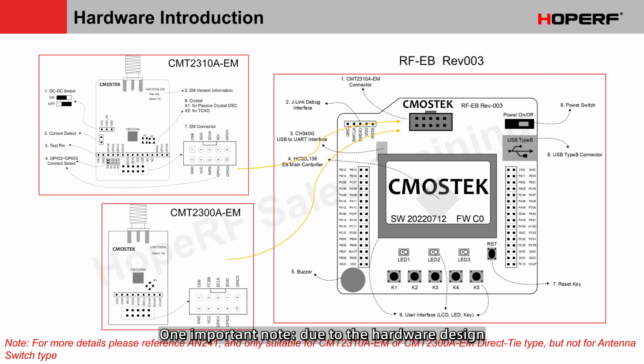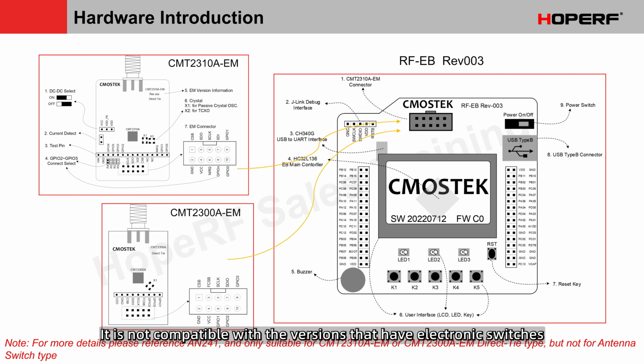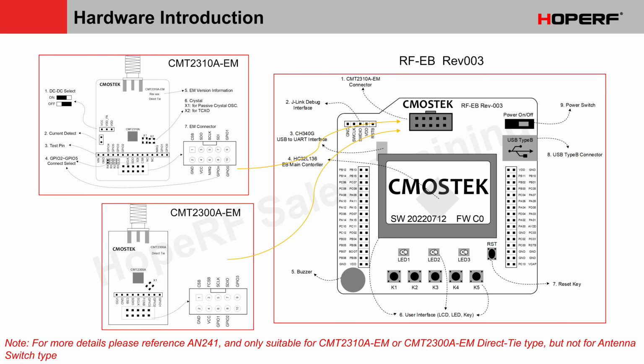One important note, due to the hardware design, this demo kit with its factory firmware is only compatible with the DirectT versions of the CMT2310AEM and CMT2300AEM modules. It is not compatible with the versions that have electronic switches. For more details, please refer to application note AN241.